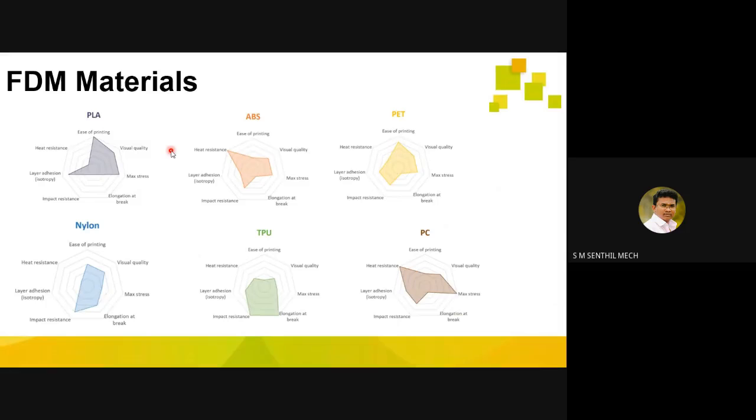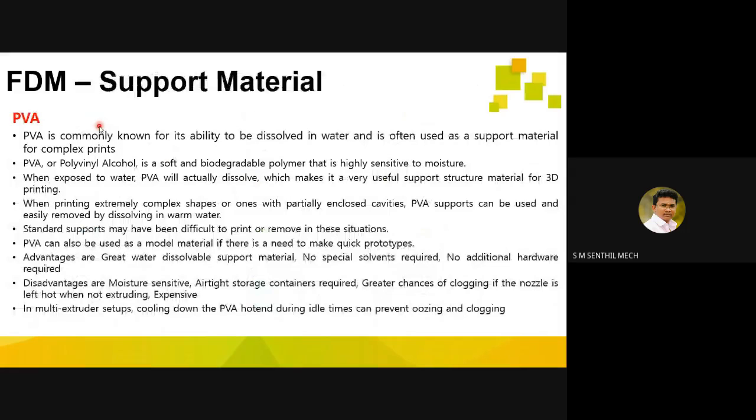We discussed this during the last class, and we also discussed the PVA material, which is a water dissolvable material, primarily used as a support material in FDM processes.